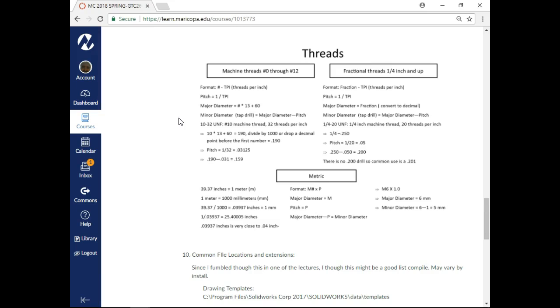Most of the 3D printing might be able to snap fit together or something that you want to glue, but most of the time I still plan on bolting my 3D printed parts together, because at this point, the speed, the accuracy, all of those things that I need for a production part aren't quite there. For a prototype, it's great. I can do some complex geometry and put it together, and yeah, this is going to work. And as soon as I put a significant load on it, snap.